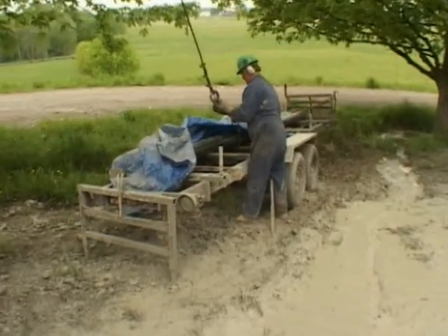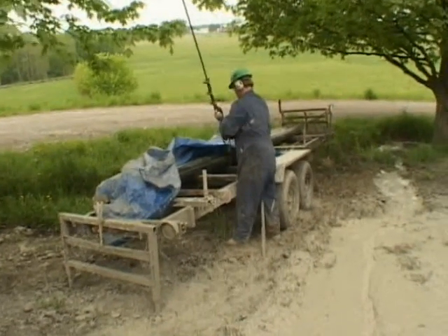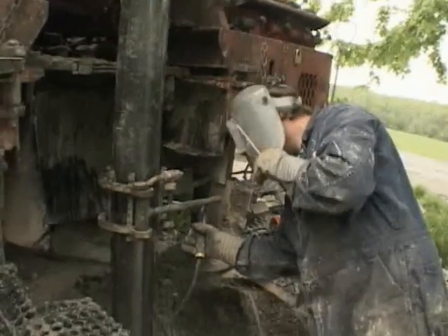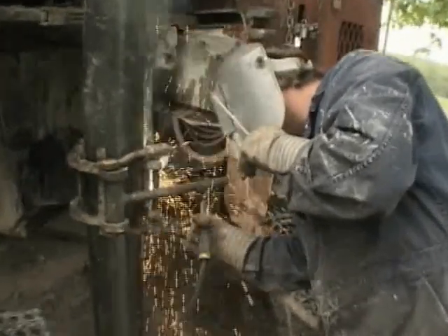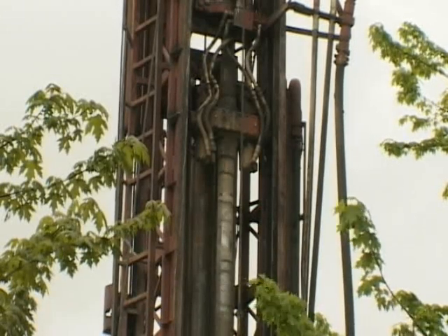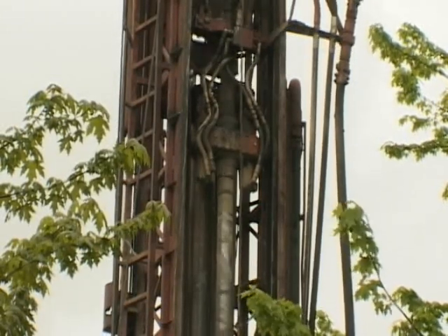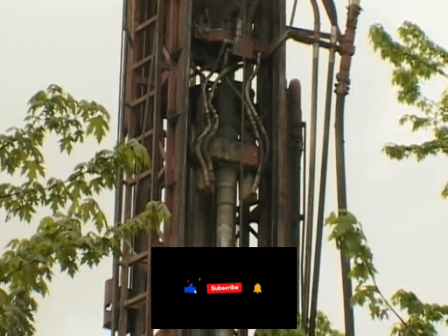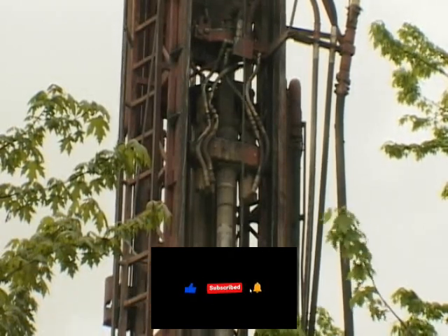The order of operations for the drill-through casing driver is drilling the borehole, advancing the casing, adding a new section of pre-assembled casing and drill rods, welding the section to the previous section, and then advancing the casing section. This drilling sequence is continued until such time as suitable aquifer is located or bedrock is encountered.